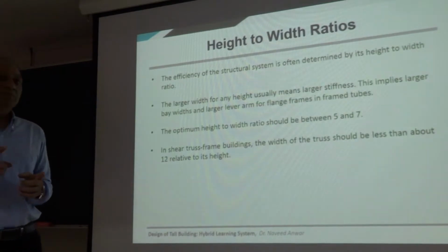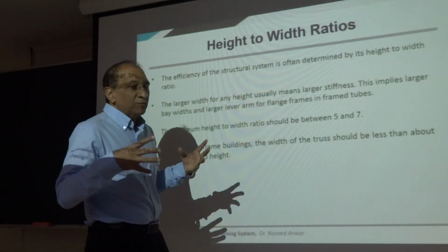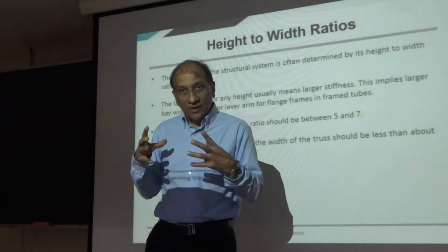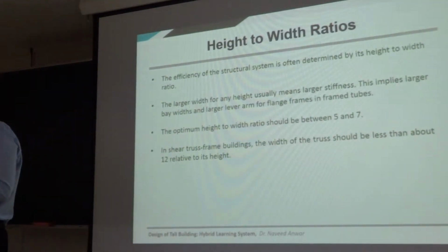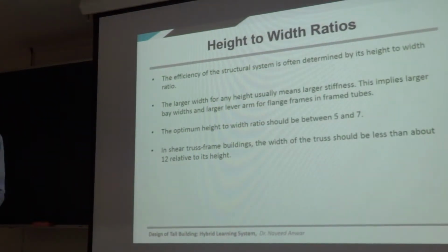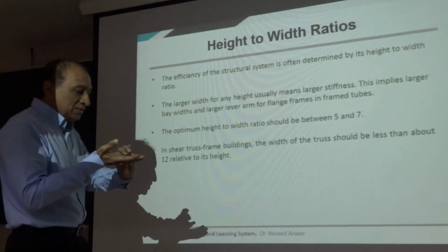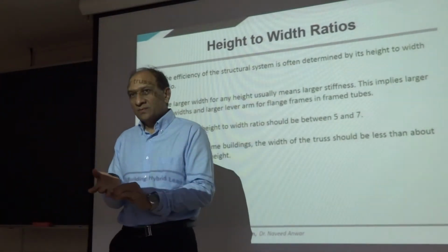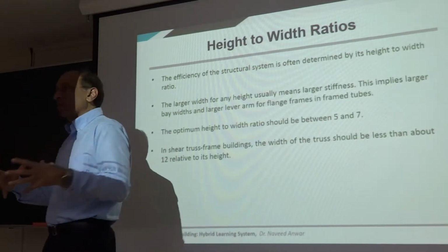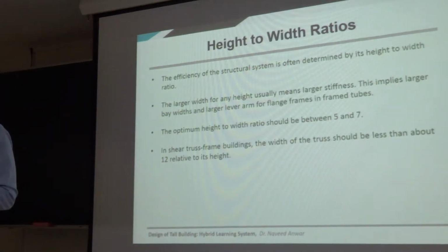Structural parts have to be really reduced, vertical parts especially, so that the sellable area, net usable area, can be increased. Okay? So you target the highest possible strength of concrete and steel, maximum, and then you target the smallest column size at the ground floor, and that's how you go up. That's the rule for preliminary sizing of columns in a tall building.